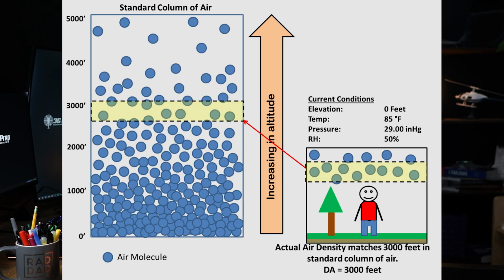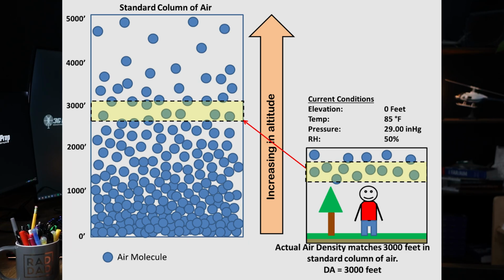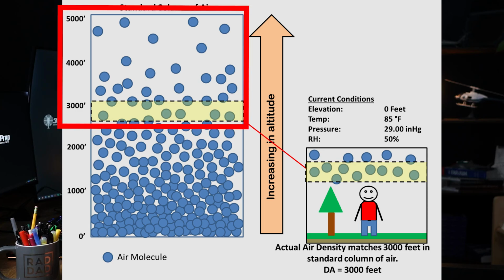The air density is the density of the air in which the helicopter is operating, which varies with altitude, temperature, and humidity. Lift is directly proportional to the air density. Higher air density, as found at lower altitudes and cooler temperatures, increases the lift. Conversely, where hot and high altitude conditions exist, where the air is less dense, lift decreases, which is why helicopters have reduced performance in such environments.